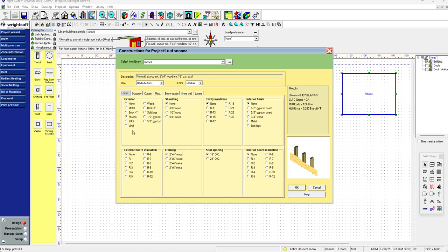So what's on the outside of the home? Do you have brick? It shows brick. Do you have stucco? Do you have some kind of vinyl siding, or wood siding, or wood paneling? Here in Arizona, it's very typical to have stucco. What kind of sheathing is there? There's almost certainly some kind of sheathing. Now, what kind is it and how thick is it? I mentioned before about cavity insulation. R11, I think, is the minimum for code, the minimum requirement according to building codes.